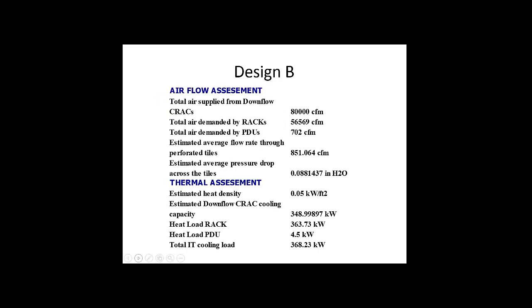So this is a summary of the input side. A little bit more here about it. We've got 4 CRACs, 80,000. They're 20,000 apiece. Total demand, 56. So again, this one was built for an N+1 case, is what I suspect. And in an N+1 case, you can see that's running pretty much at capacity. N+1 would be, if one of these guys was down, you'd be running 60,000 at 56. So now, when they're all up is when you have the issue, of course. When they're all working, you've got an RTI that is way too low.